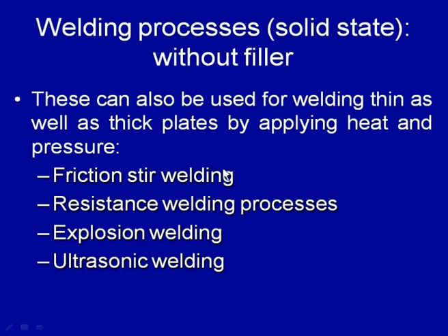In all these welding processes, if we see, the material is not brought to the molten state. However, in resistance welding there may be a semi solid state condition, but the pressure is used to consolidate things, but no material is added from outside, and that is why all these welding processes are generally carried out under solid state or semi solid condition, where filler material addition is not done, and these welding processes include friction stir welding, resistance welding process, explosion welding process, and ultrasonic welding processes.